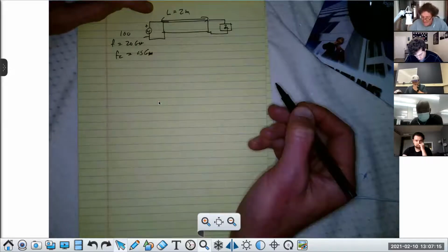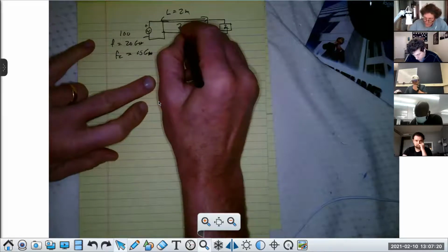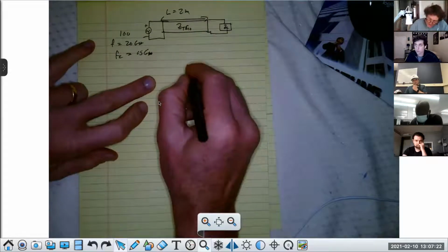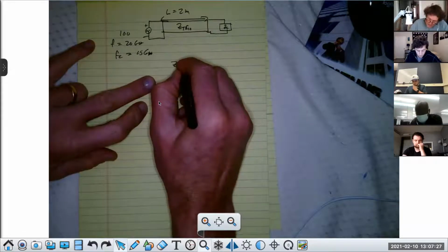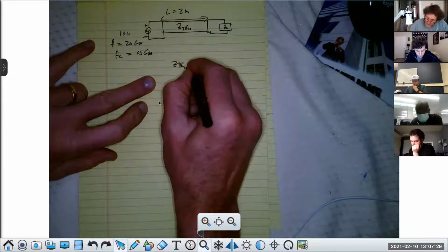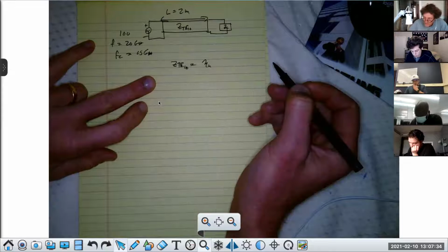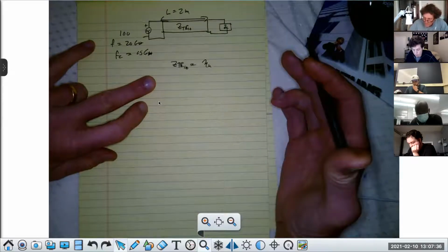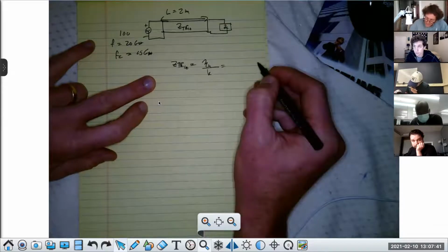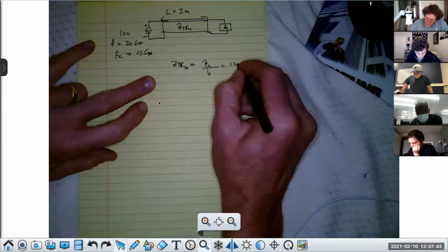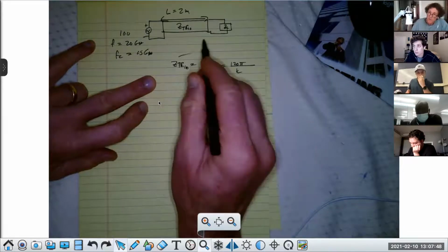All right, so the next thing I need is the impedance of the TE 10 mode. That's going to be the characteristic impedance of the guide. ZTE 10 will be equal to the characteristic impedance of the waveguide with the material inside the guide, unbounded, divided by K, right? And that's really 120 pi, it's just the free space because it's filled with air, over K. Now I have that. I'm going to do all this. You with me?